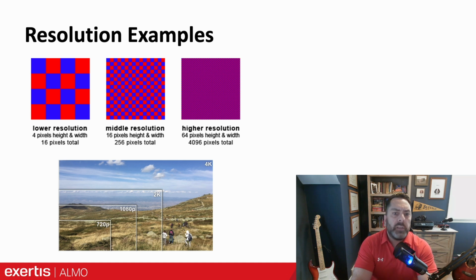Pixel pitch indicates how close together the dots will be, as mentioned. So for example, an LED wall with a pixel pitch of 10 means there will be 10 millimeters from center to center from one dot to the next. A pixel pitch of 2.5 is 2.5 millimeters between dots, and so on. As of this moment in 2025, many DVLED manufacturers are offering pixel pitches as fine as 0.7 millimeters. To give you a point of reference, a 100-inch 4K traditional LCD TV will give you an approximate pixel pitch of 0.45 millimeters.